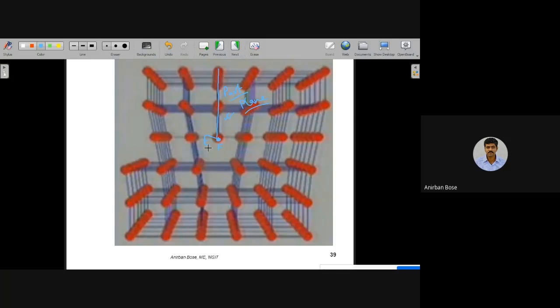But remember, practically in a crystal, edge dislocation is not created the way I have described. I have just described it so that you can understand what is edge dislocation. It is not that someone is actually cutting with a knife and giving a push. It is during manufacturing processes, during different operations, that these kinds of edge dislocations are actually created. Okay, it is not created in the way that I have shown, I am just trying to visualize what is edge dislocation. Okay, so this is the edge dislocation.